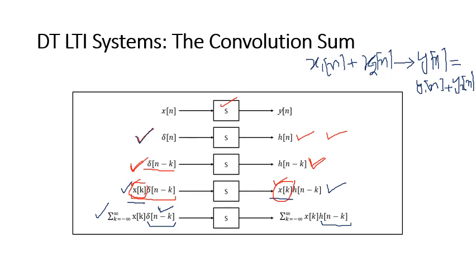If you give it something now, it produces some output. If the same thing is given 2 days later, it will produce the same output. Why? Because the system is not time varying. So the shift in input produces the same shifted output. And this is the scaling. If input is scaled, output is also scaled by the same amount. If input is summation, then output is also the summation. This we have done while doing the linearity property.